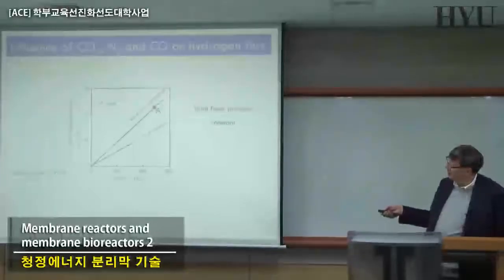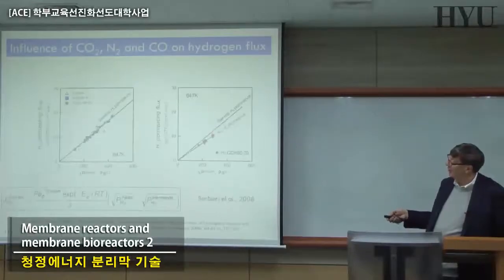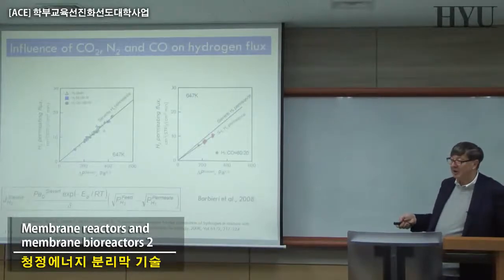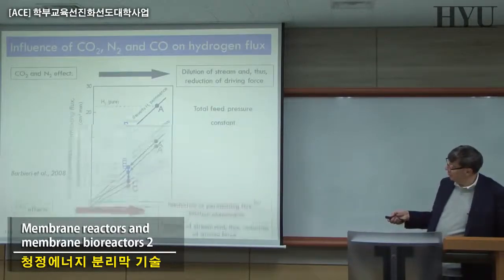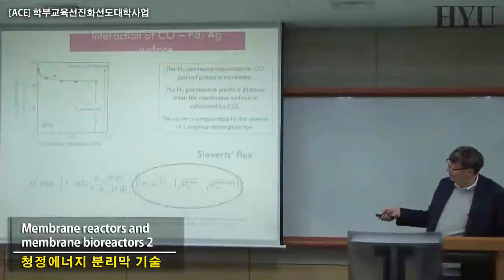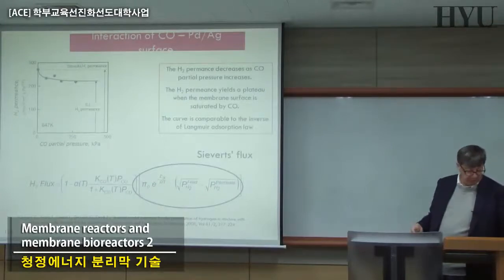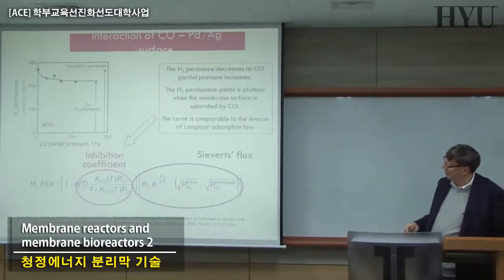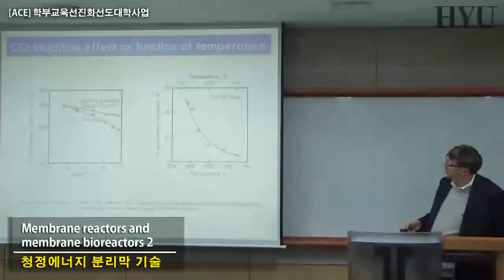And today this work has been recently done, and if the model has been validated, basically, it's telling you that we have to consider this kind of situation also in gas separation systems, which is not marginal, because this parameter here is affecting not 0 or 1, but 10, 15, 20% of the overall permeance of hydrogen, these inhibition coefficients, which is not just concentration polarization.